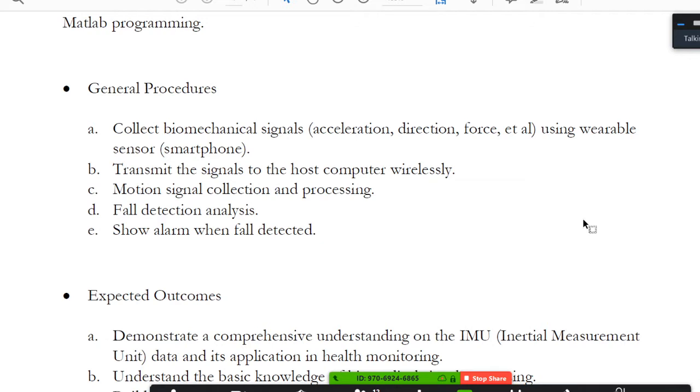So normally the technique is like, first you need to get rid of the DC component. The DC component is from the gravity. Why is it from gravity? Because even if you have no acceleration, you still have an input signal. The input actually is the gravity. Gravity is 1g, so even if you have no motion, you have a signal.